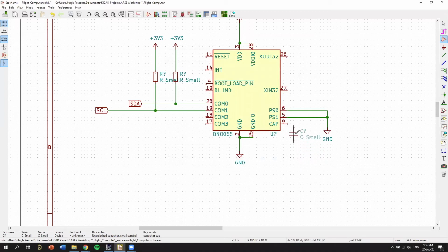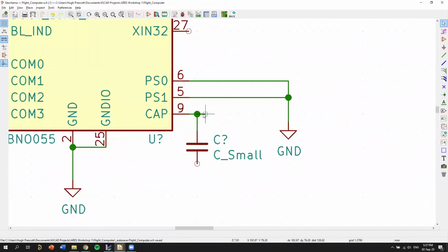For example, ceramic capacitors, it doesn't matter which way you put them, they'll just work. Capacitors of this size are normally ceramic, they're pretty small. But electrolytic capacitors are much bigger, with a much bigger farad value, and you have to put them around the right way. They're not going to operate both ways for you.